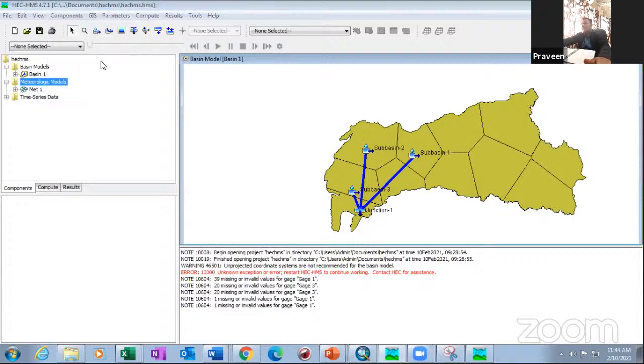Then how to validate it? Of course, as your question says, if discharge is not there, then for validation you need the discharge values, or else there are some other techniques. There are many other techniques: you can develop rating curves for ungauged catchments. So you can use the ungauged catchment concept, develop your rating curves, and then validate there. That's a totally different process and a very long process. I'll help you out if you are interested in doing this for ungauged catchments.